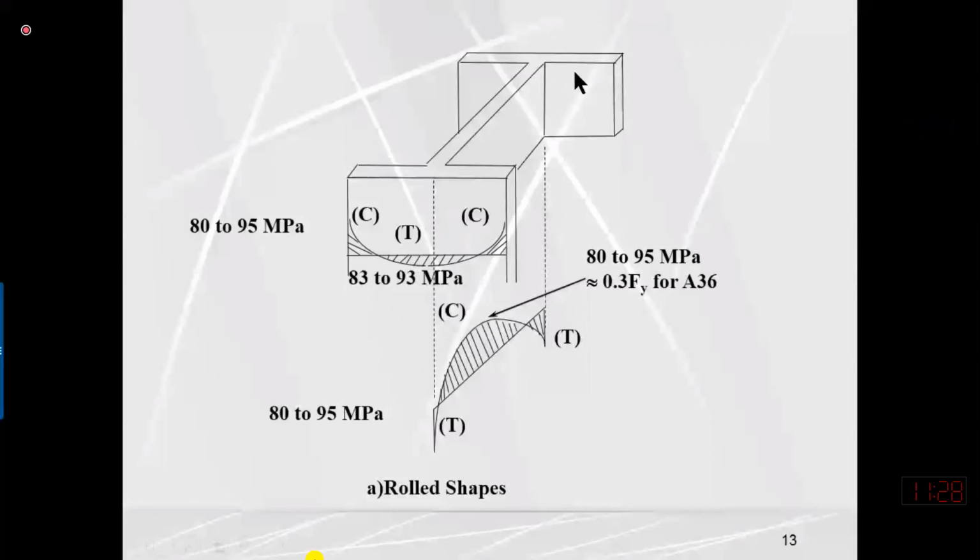The flange tips and the center area of the web will cool first because they have more surface exposed to the environment. The junction will cool at later stages, or slowly, because here the material is surrounded by the web plate and flange plate. It means the flange tips will cool first.